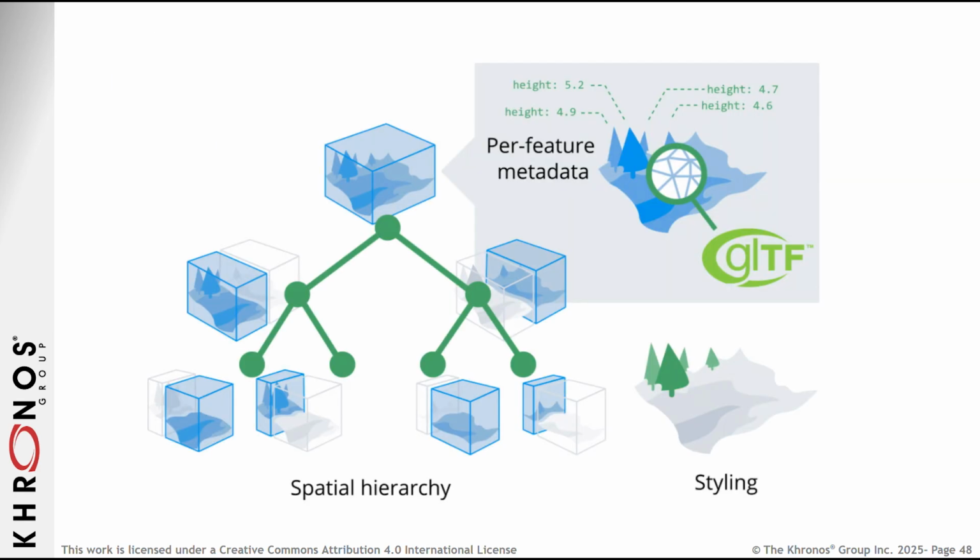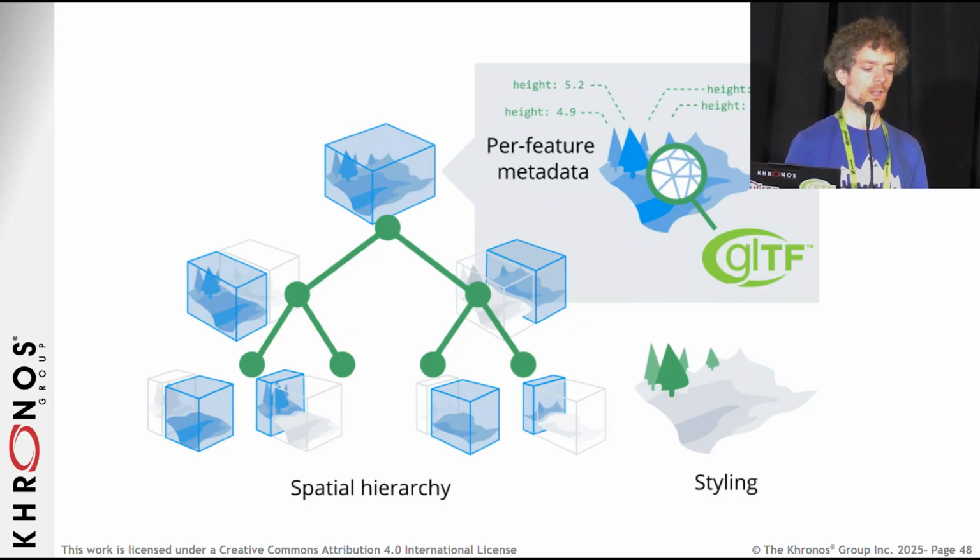Ultimately, 3D Tiles defines the spatial hierarchy. So you have a root tile, then you have children tiles, and so on. There's a concept of geometric error, which tells when a tile refines to its children. And then every single tile is really a glTF model. So the root tile is a glTF, and the leaf tiles are glTFs. The glTF is what contains the actual geometry, textures, and materials of the content of the tileset. And then your glTF can have metadata inside of it as well, and you could do runtime styling.